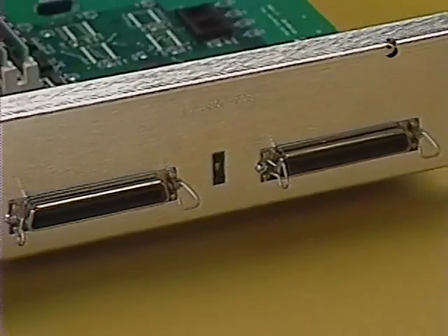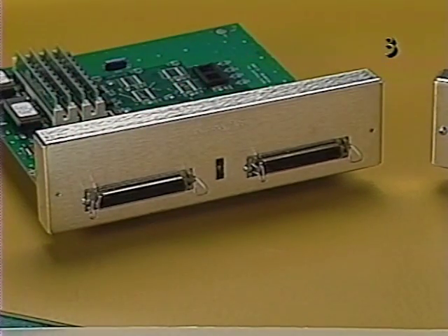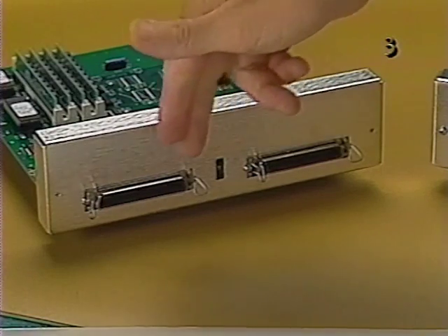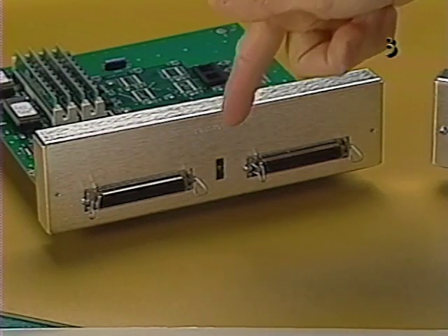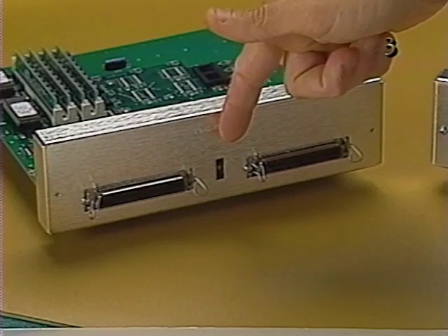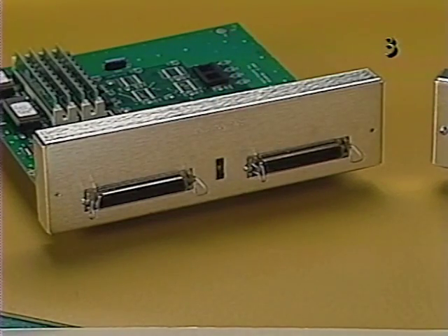The Personal LaserWriter SC I/O board panel has 2 ports and 1 switch. These are the SCSI ports. The Personal LaserWriter SC can only be used as a non-networked SCSI device. And this is the SCSI device identification number pinwheel. This pinwheel is identical in appearance to the pinwheel on the Personal LaserWriter NT used to reset dip switch settings. Remember to select an appropriate SCSI identification number when setting up the Personal LaserWriter SC, as you would with any SCSI device.